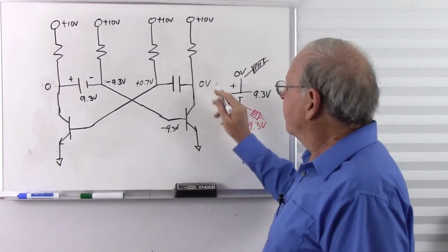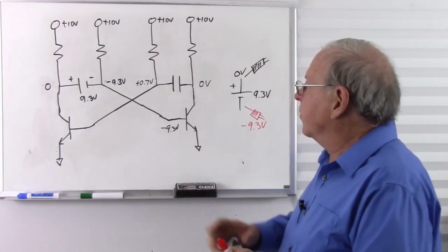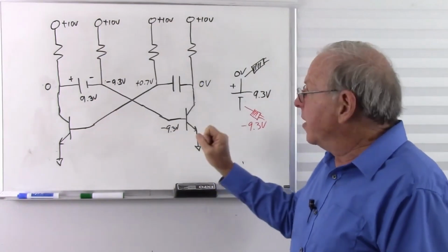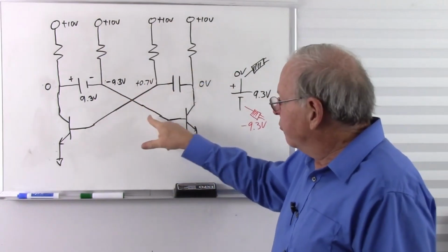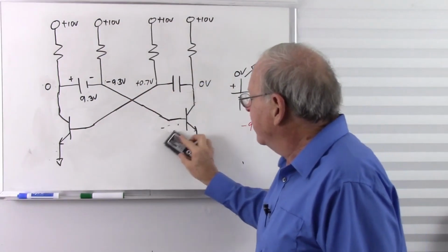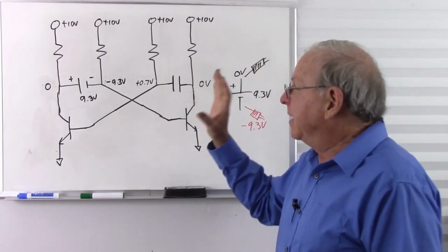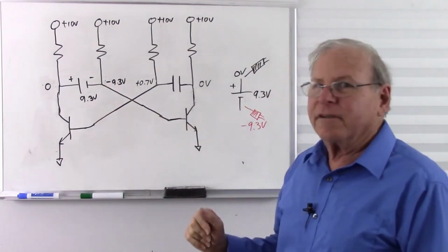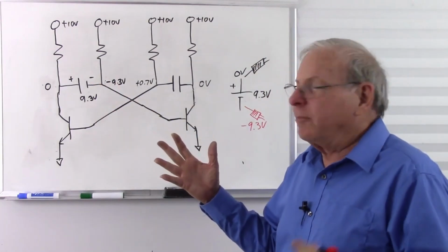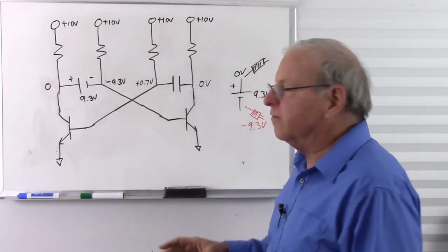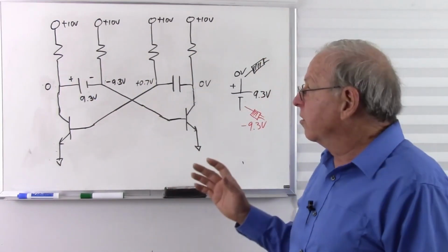Turns off that transistor, and we just go through the cycle back and forth again, just like before. So if we make our Astable multivibrator with bipolar junction transistors, we get this reverse voltage on the base. Does it change the way it works? Nope, still works exactly the same way, but it's interesting that we do get that negative voltage, but other people explaining Astable multivibrators will bring that up, so I just want to make sure you understand why we get those negative voltages there. But otherwise, the circuit works just the same.